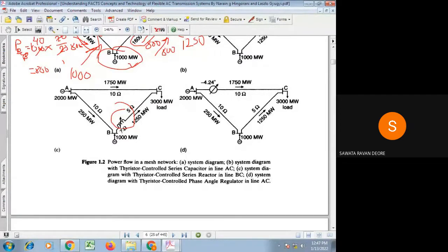In series with that, we can add up the additional reactance. Here they add 7 ohm reactance, which is variable they keep. Means according to operating condition, if they need to change it, then they can change it. That overall reactance of this line is now controllable by means of this FACTS controller device. Here we just show the static series reactance, but it can be a power electronics based voltage source or capacitor or reactor or anything else that we will see in detail later.